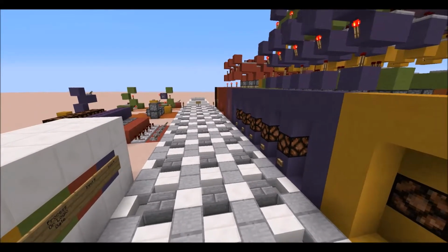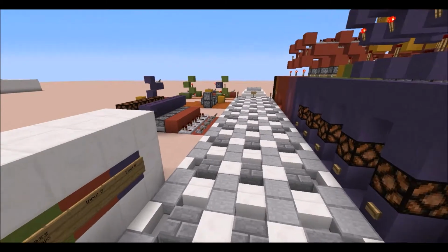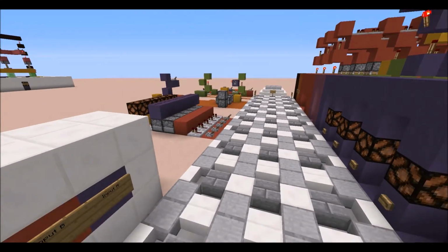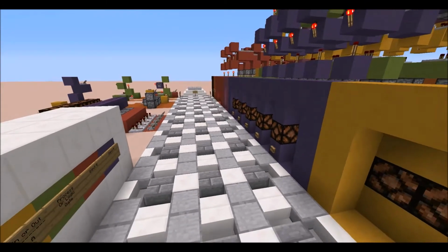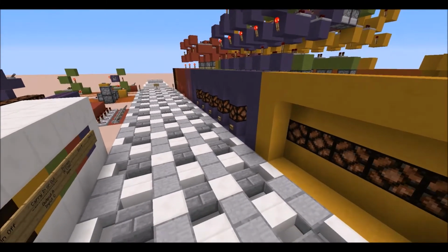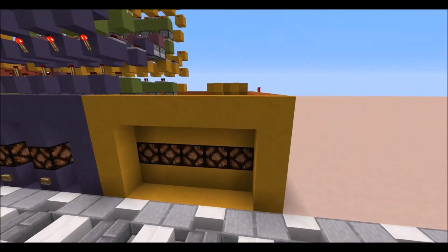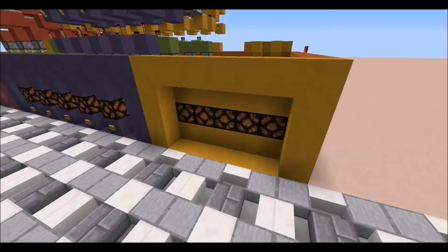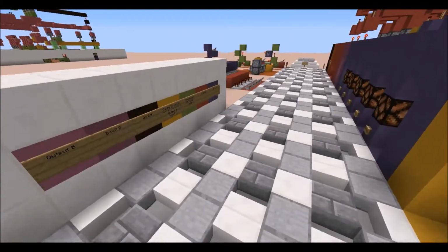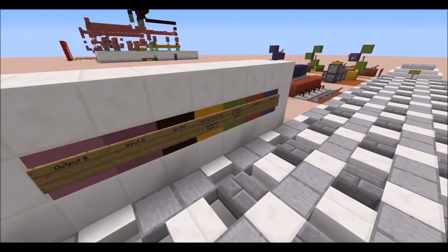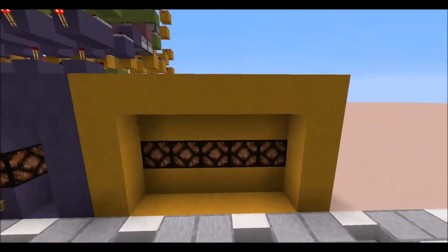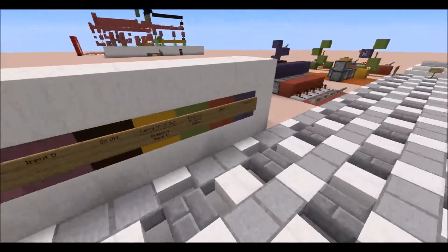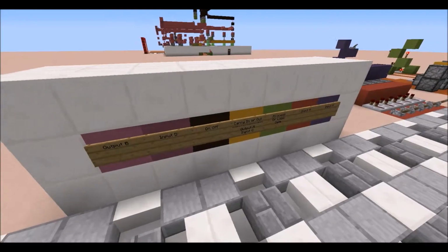But three out of the four of those only consist of one digit in binary. But 1 add 1 equals 2, and 2 is 1, 0 in binary. So the 1 will act as a carry out, or a carry output, and go back again into the sum of the next one as the carry input. And that's why I use yellow for that. But yellow can also be output C, the main output like this one here, or a third input.